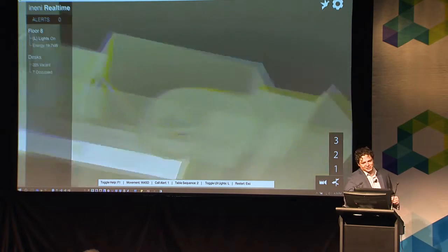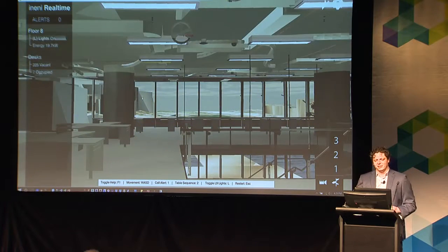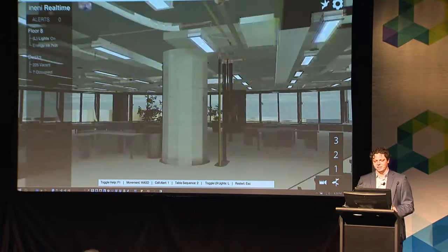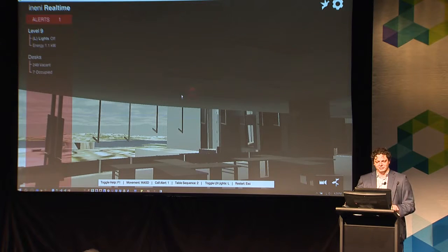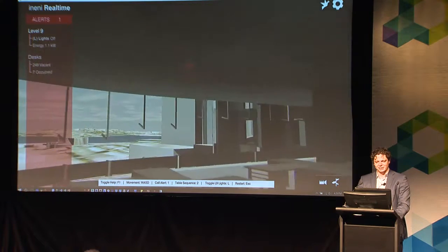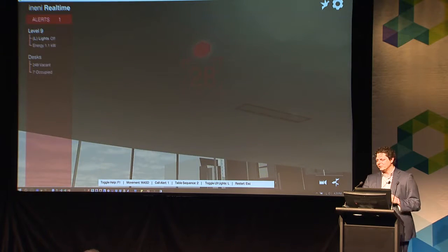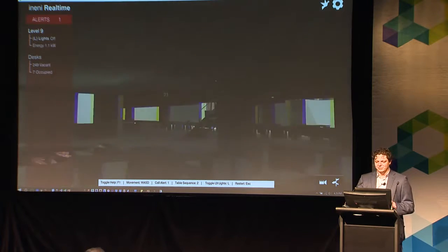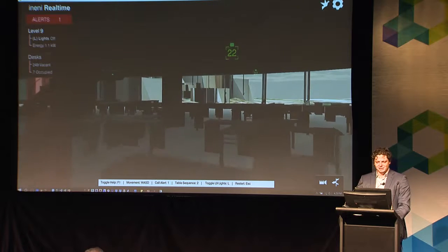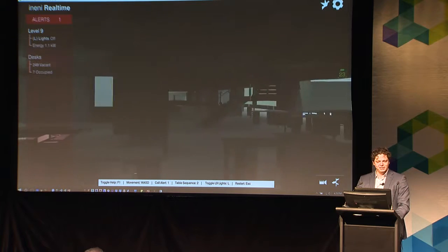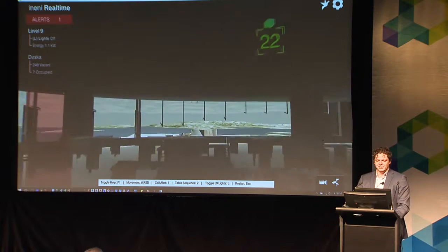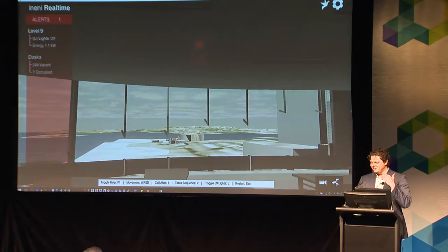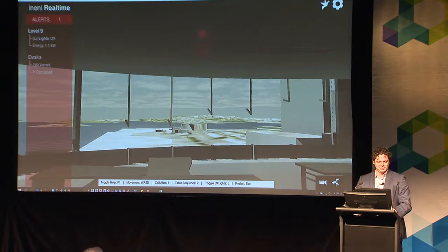So that got us this job, but they wanted a lot more. The concept was, how do we go further with this? They wanted an alarm to happen, and you click that alarm and it takes you to the relevant point. You know, there's a temperature sensor currently reading 28 degrees Celsius. We look around and we see that all the other temperature sensors read 22, 22, 23. So in an open plan space, we could make a pretty quick assumption that that's probably a broken sensor. And they could then drill down to the building management system and decide some stuff.